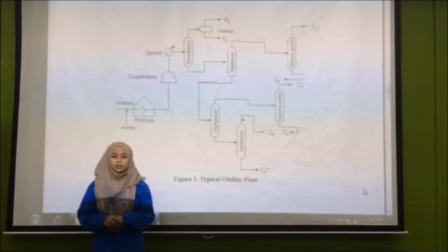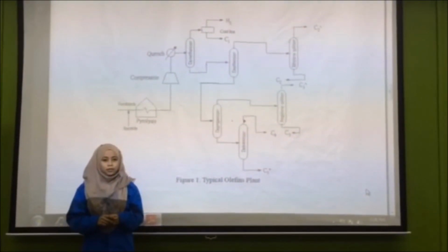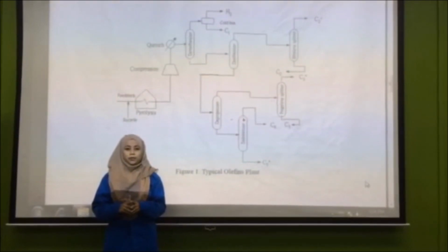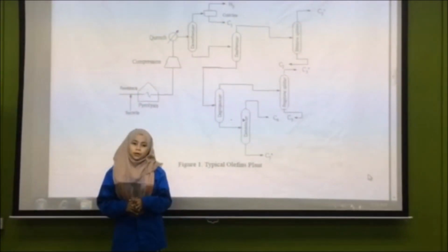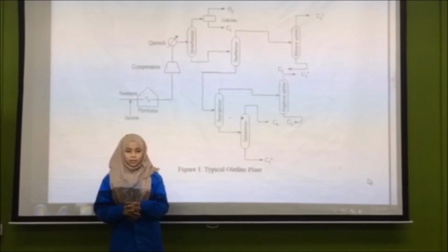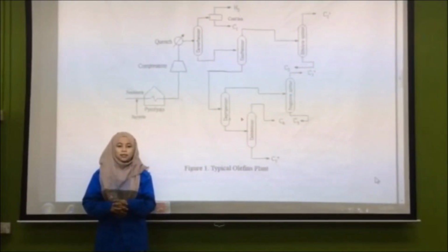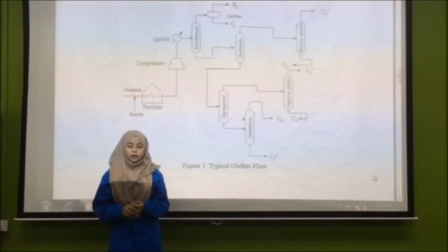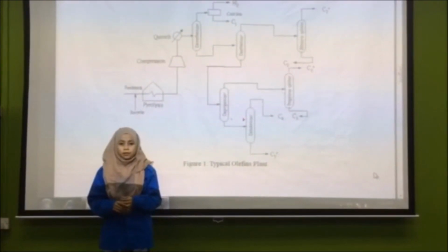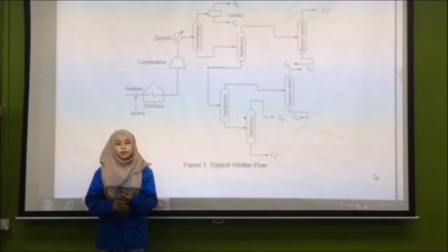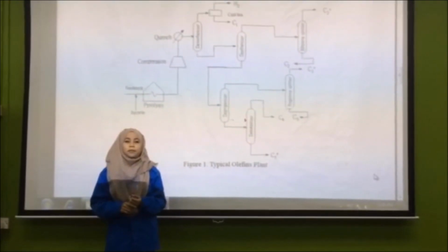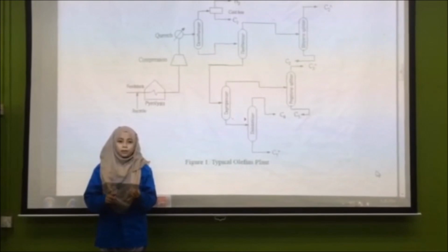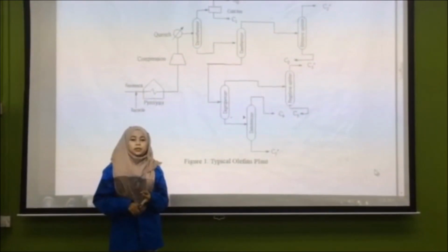Chemical processing: it has been variously estimated that the capital investment in separation equipment is 40 to 50% of the total for a conventional fluid processing unit. Of the total energy consumption of an average unit, the separation steps account for about 70%, and of the separation consumption, the distillation method accounts for about 95%. In general, initial design of a distillation tower involves specifying the separation of a feed of known composition and temperature.